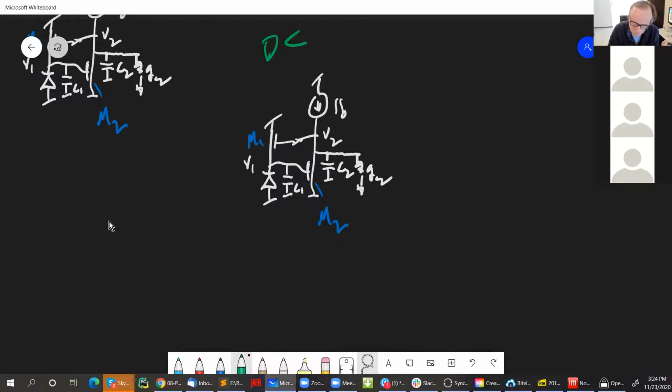And for that, we actually need to replace this transistor with a PFET. So let's put in a PFET there and put a bias voltage on it. It just makes it easier to compute the voltages if we have a bias transistor there with a bias voltage on it, VB. That's some voltage VB away from VDD. It's a PFET, so we only care about the voltage, not relative to ground, but from VDD, right?